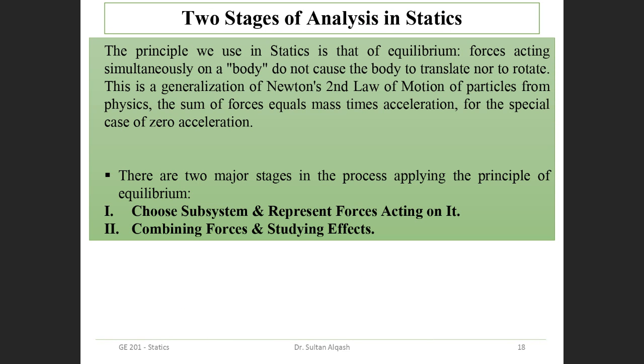Okay, simple. So in general, in statics, we have two stages of analysis. We said that the principle we use in statics is equilibrium. So forces acting simultaneously on a body do not cause the body to translate nor to rotate. This is a generalization of Newton's second law of motion. The second law of motion is just a generalization of the first law of Newton, right? If you assume that there's no acceleration, zero acceleration, that means we have sigma F equals 0. Clear?